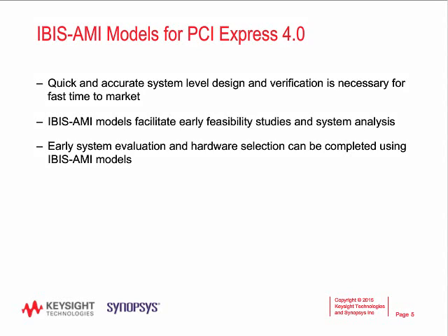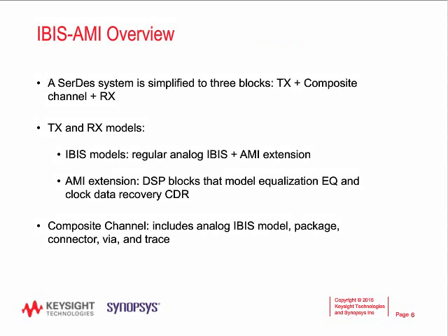At PCI Express Gen 4 rates, channel equalization needs to be incorporated and modeled algorithmically, which is where the IBIS-AMI model excels. Peggy will now discuss the IBIS-AMI model. Thank you. So now that we have discussed and agreed that we're going to be using IBIS-AMI models for modeling of PCIe 4 transmitters, let's actually talk about the SerDes system in general.